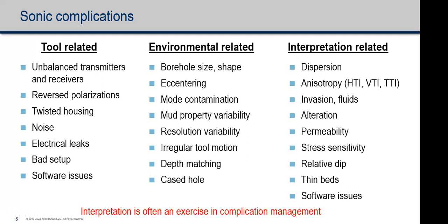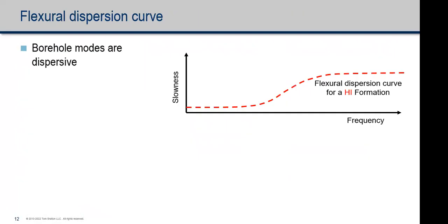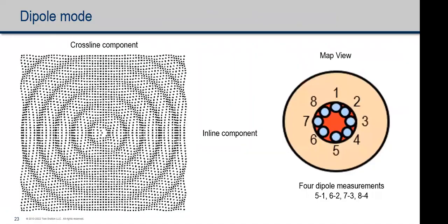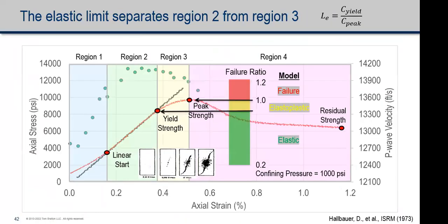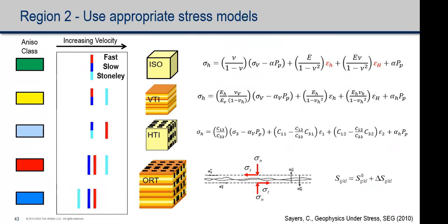Sure, thank you, John. Well, the question is a traditional one. When we look at the equations for calculating stresses, you had a slide on this, and in traditional workflows, people typically take dynamic properties and then correct them for static properties to get Poisson ratio, Young's modulus, anisotropic stiffness and Poisson ratio. But in a triaxial cell that you showed, the apparent linear slope during the elastic regime.